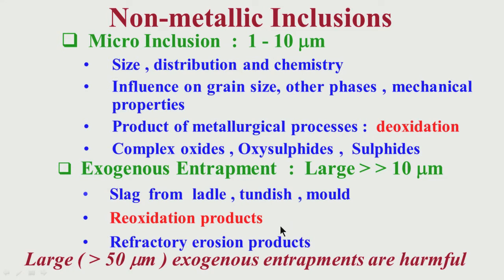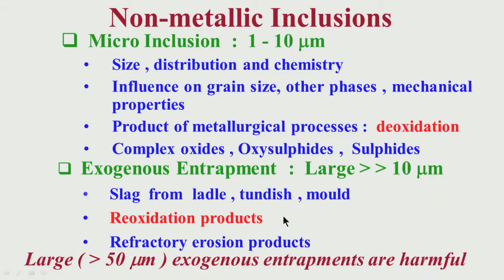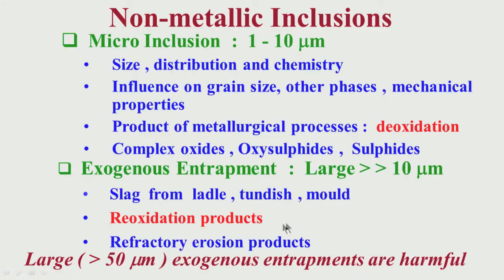You have aluminum in steel, we may have titanium in steel, we of course have iron in steel, we have silicon in steel. So, reoxidation products can be alumina, can be silicon oxide, can be to an extent iron oxide, can be titanium oxide. These will create a lot of problems, and please try to remember these reoxidation products like alumina, titanium oxide, they have very high melting point.